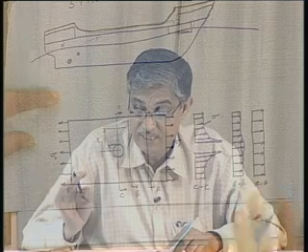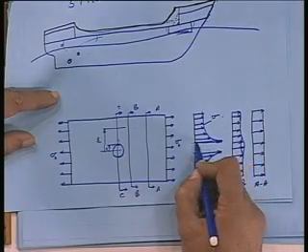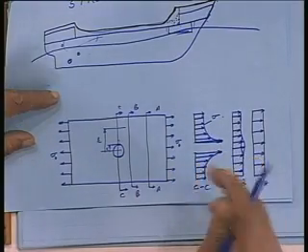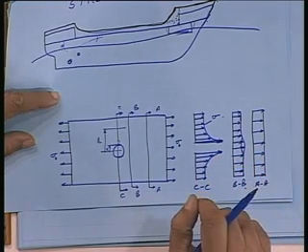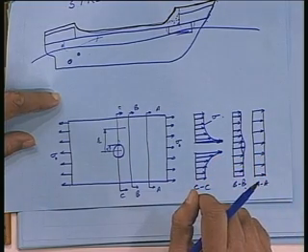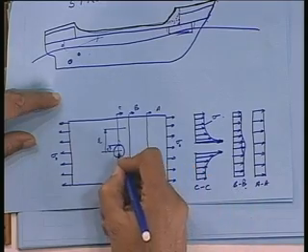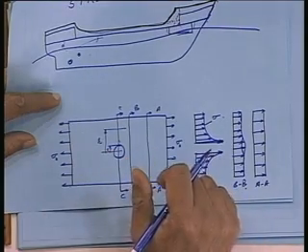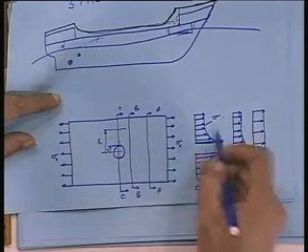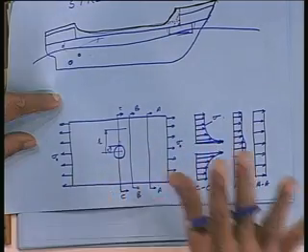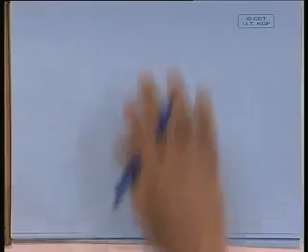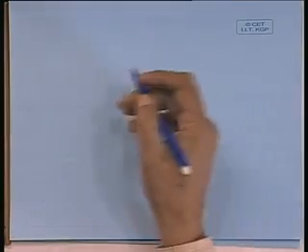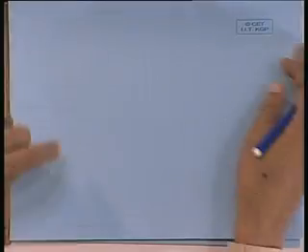Again, from elasticity you will find that this stress which is here will get slightly tapered down. Okay. So if you are having a smaller hole, more concentration will be there. If you have a bigger hole, then the concentration is reduced. Now this phenomena I will try to explain you.